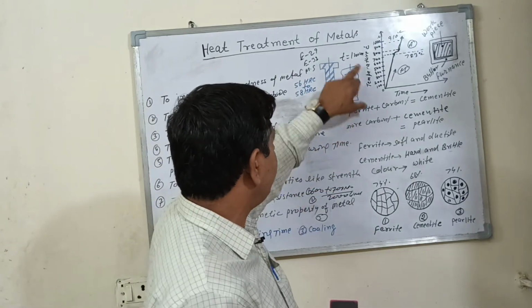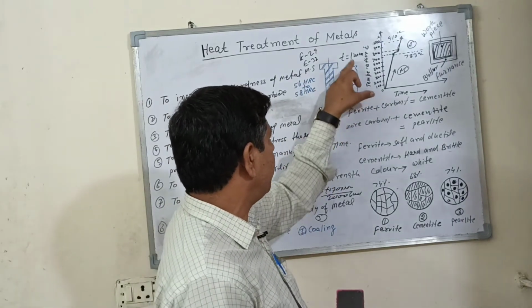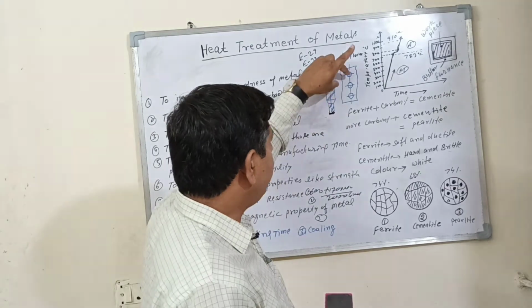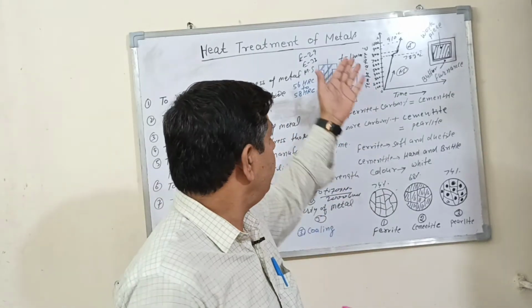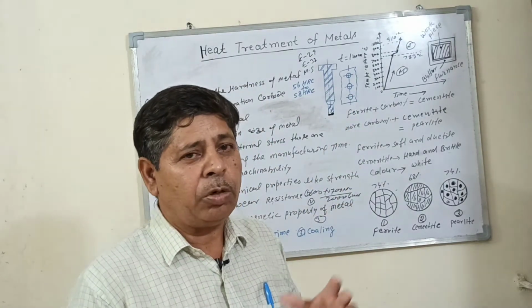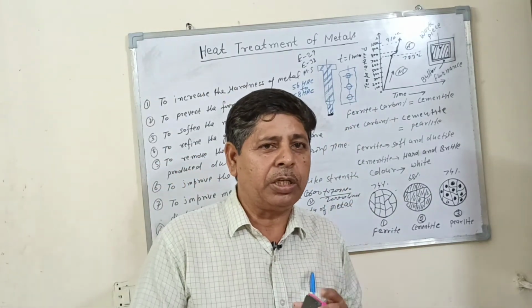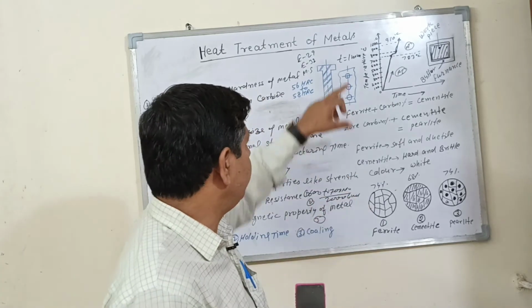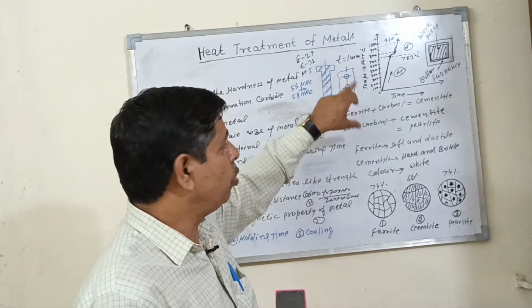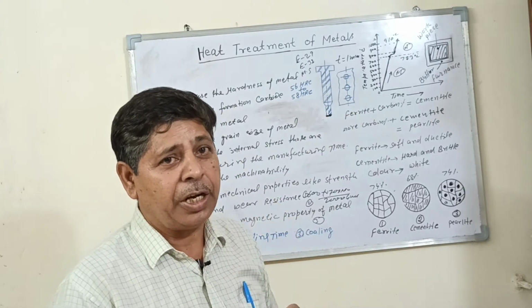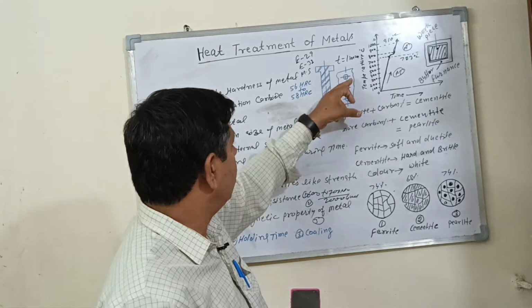If you want to perform a number of holes in a sheet with a 1 mm thickness, the holes can be performed by the drilling machine. Using the drilling machine you cannot get high grade accuracy and you cannot get mass production. Then we will make this type of punch to perform this type of holes to get mass production and get high grade accuracy on the hole.